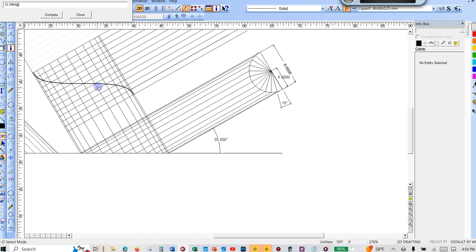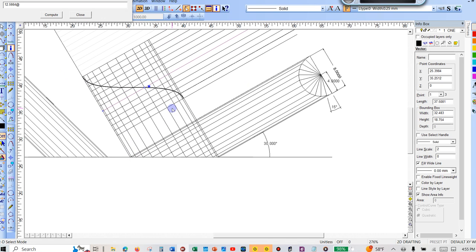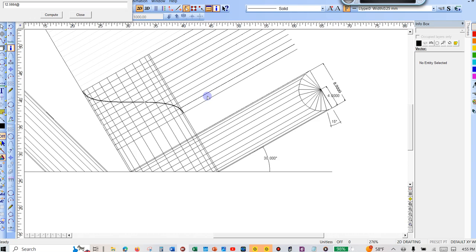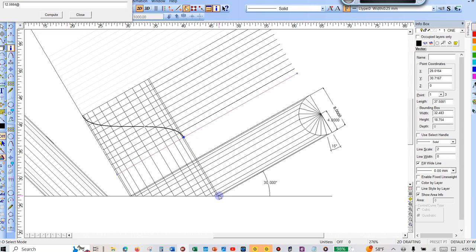All it is, you just take this and reduce it by the thickness here of a 1/4 inch pipe. I don't know if I'm going to get into that. But you've got to take that into account when you do the pipe, especially this inside corner, because if you cut it wrong, it'll get really short. And then it just fits right if you do it.